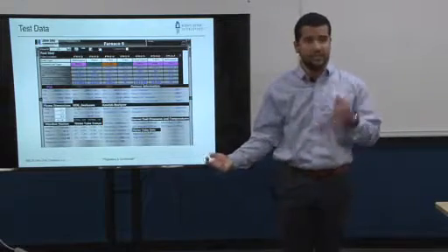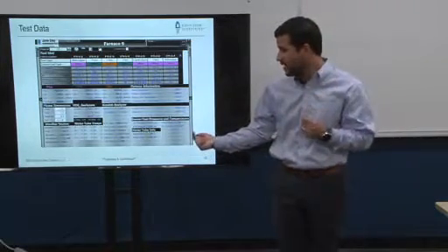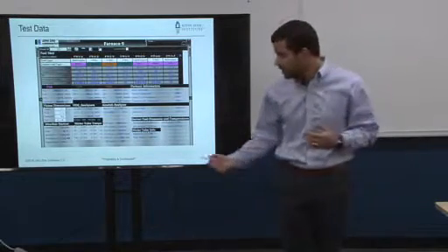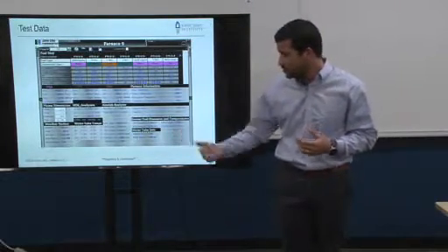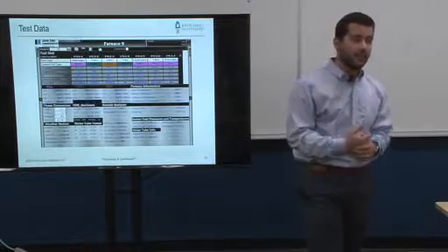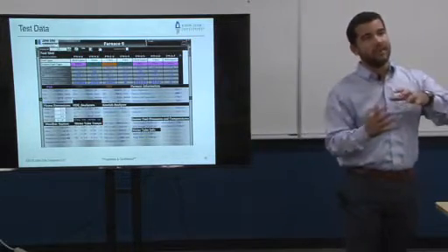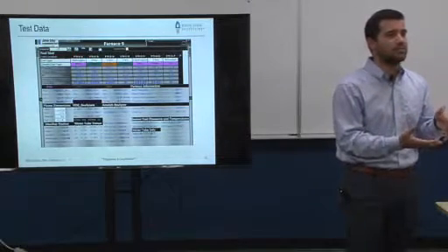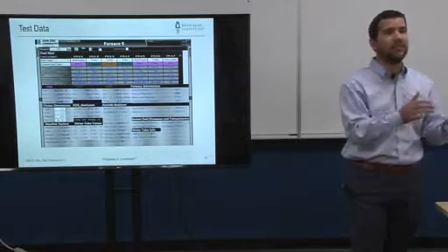In this case we also need that, so after you have that fuel blend, it goes to a heat exchanger, because this particular process happens to have fuel temperatures that were greater than ambient. You can see that the PSA temperature here was 314 degrees F. So after they get all mixed, they go to a little heat exchanger, we typically use a steam heat exchanger, they get heated up and then fed into the burner.